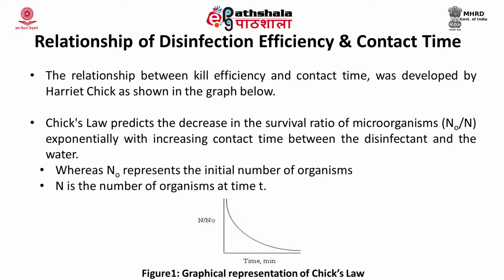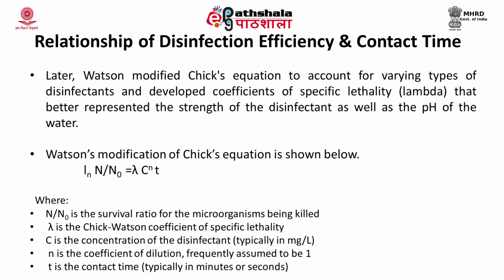Chick's law predicts a decrease in the survival ratio of the microorganisms, which is shown on the graph on the vertical axis, exponentially with increasing contact time between the disinfectant and the water to be disinfected. Later on, Chick's equation was modified by Watson to account for varying types of disinfectants, and he developed the coefficient of specific lethality, denoted by lambda, that represents the strength of the disinfectant as well as the